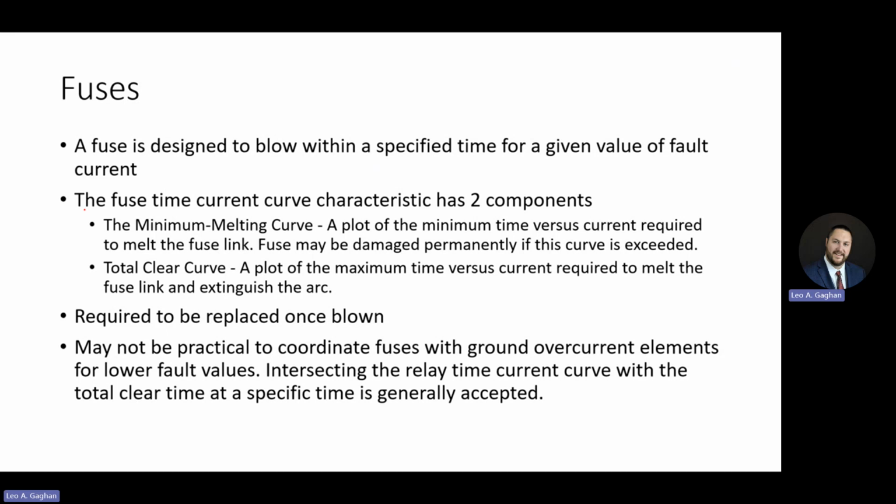As compared to, let's say, a recloser. A recloser knows that most faults are temporary, and it actually automatically recloses and is successful most of the time. Maybe it was a squirrel that got in between an energized conductor and a grounded piece of equipment.